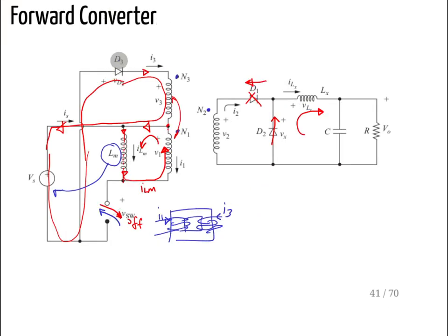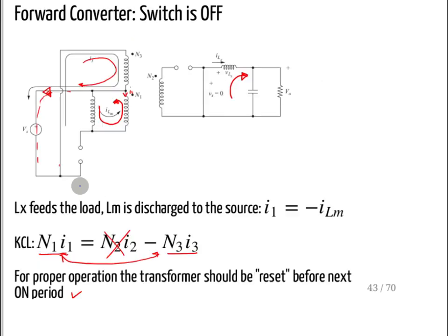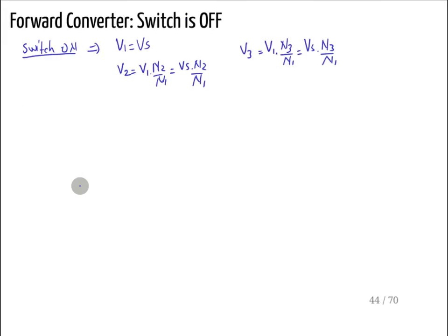Mathematically, if you would like to find the voltage along that one, you can have one voltage here and another voltage there. So you can write VD3, the diode 3 voltage, is equal to minus Vs minus V3. And you can see it is less than 0, so D3 is off during the first time.